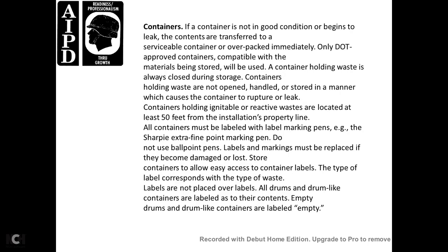Containers are not good if they begin to leak, and a container transported to the surface that leaks should be overpacked immediately. Approve the container for the capability of the materials being stored. Ensure the ability of the container to hold the waste. Always close it during storage. Do not open the handles, and store containers in a manner that covers them against rupture or leak.